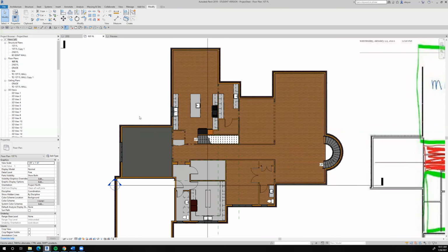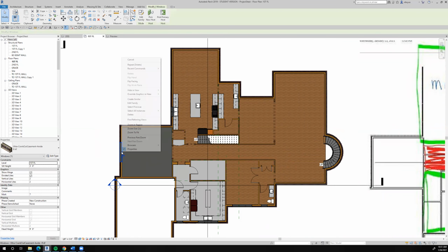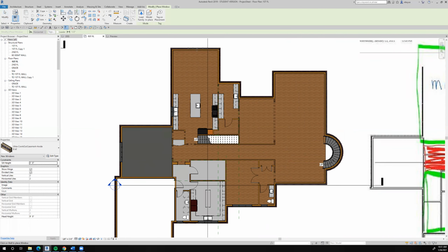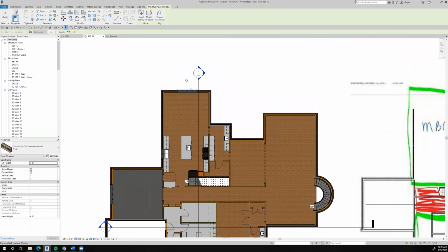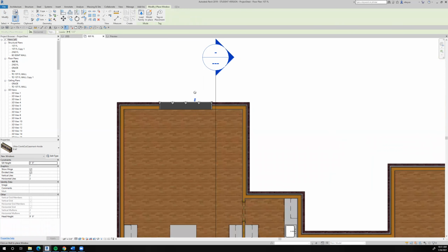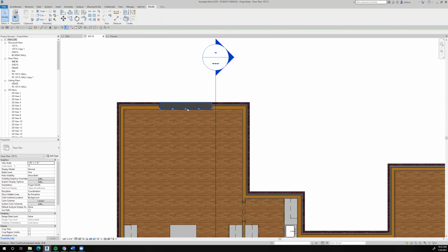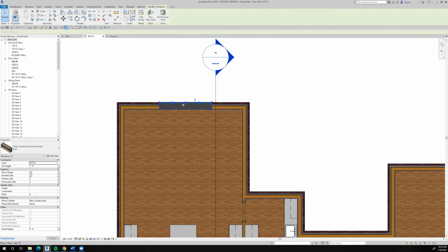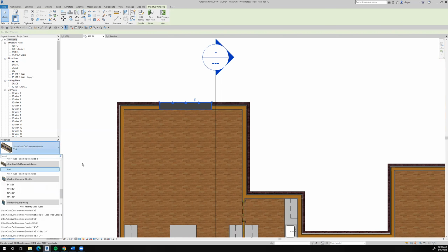I'm going to put, all right, let's do that same thing over here. Create similar. And we'll put those windows right here. I like that. You can see the windows are on the outside. Oh, no, that's definitely not correct. The windows should be flipped out there, and then my offset for that should be 4 inches.